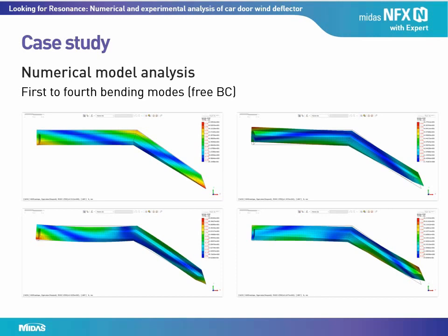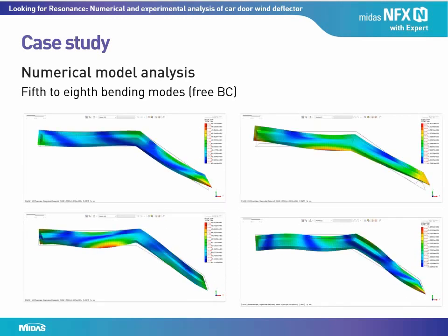First four bending modes are presented in this slide. Another four bending mode shapes are shown in this slide. From these mode shapes, we can avoid mounting the sensor near or on nodal lines as illustrated in the warm-up example.